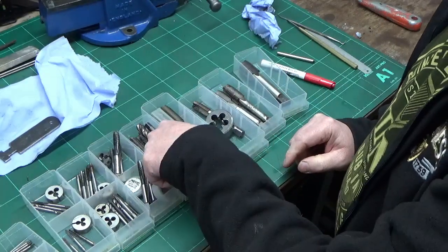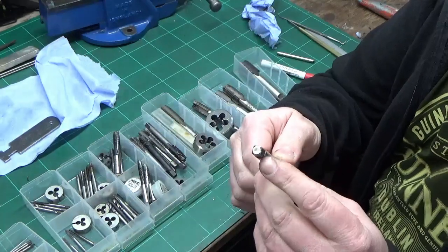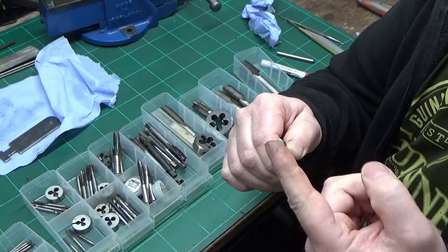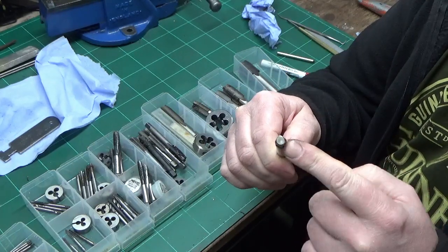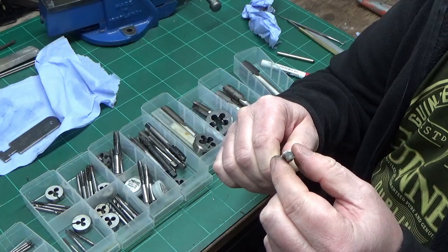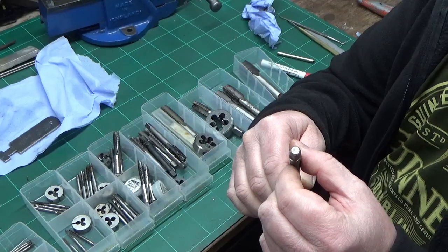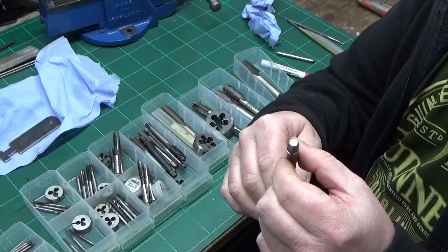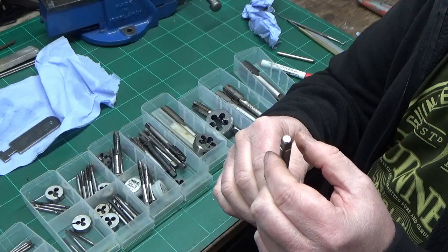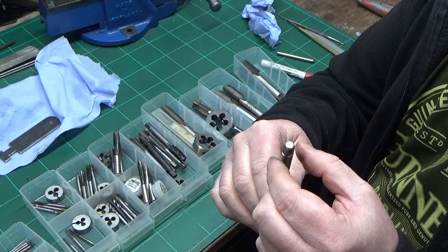So the problem that gives me, if I go to my biggest square, which is this one on the M12 tap, if I look at the size of the cup I need to cover that end of that tap, that's probably far bigger than the internal diameter that I've got to play with inside the unit itself, because don't forget my other constraint is I want it to fit in my milling machine chuck and my lathe chuck, which means the OD of the tap follower can only be 13mm.